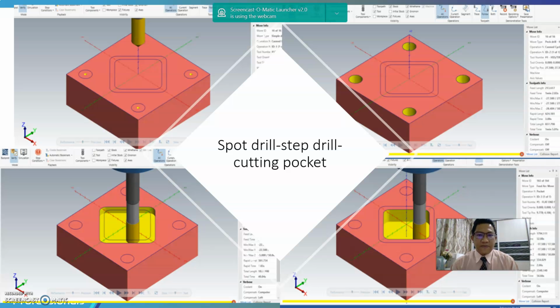-1. And then the second one is the step drill. Figure number 2 is the step drill, cut parameter cycle, drill, linking parameter and clearance, and lastly the drill, with breakthrough amount 0.4. And the third figure is the step for cutting the pocket. The material and the cutting tool are ready to cut the rectangular pocket on the milling machine.